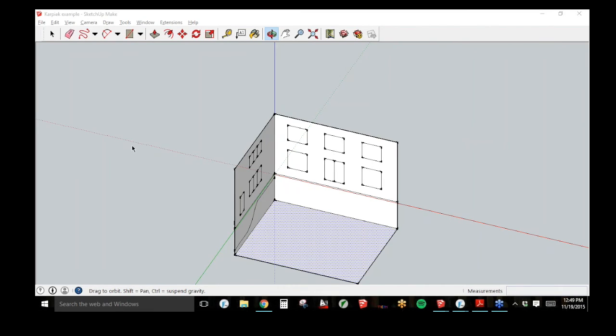If you had a concrete outside porch that was attached to the foundation, do you account for this in the SketchUp model or separately as a thermal bridge in WUFI Passive? That would be a thermal bridge, yeah. So you would use THERM to calculate the heat loss if you had a continuous concrete slab. I don't recommend doing that. I recommend breaking that concrete slab up between, like if you had a slab on grade condition and then an outside porch. So yeah, that would be a different condition. You would not need to draw this in the 3D visualizer if it's a porch outside of the thermal envelope.